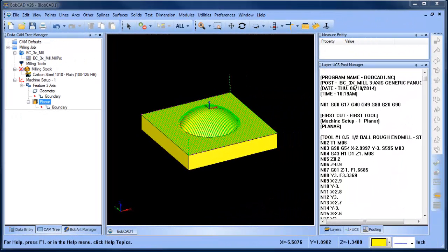So today I wanted to talk about 3D toolpaths, specifically our planar toolpath, and the code output that you can expect or customize when it comes to machining radiuses. Now, by default, the software is set up for linear interpolation, and that's what I have here.